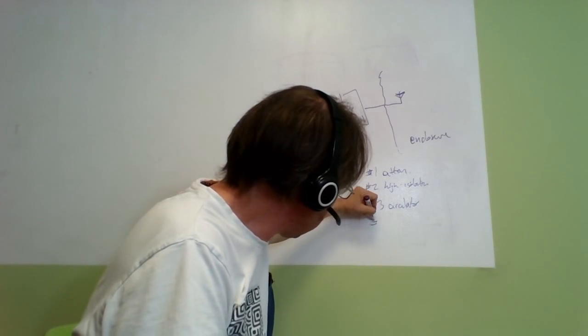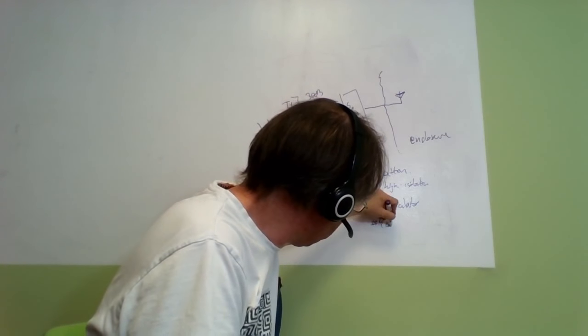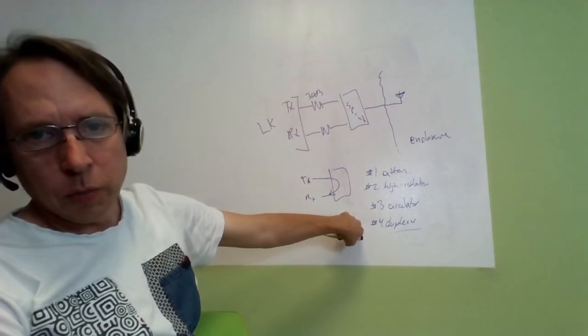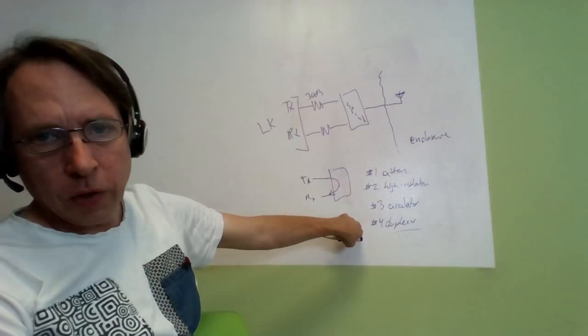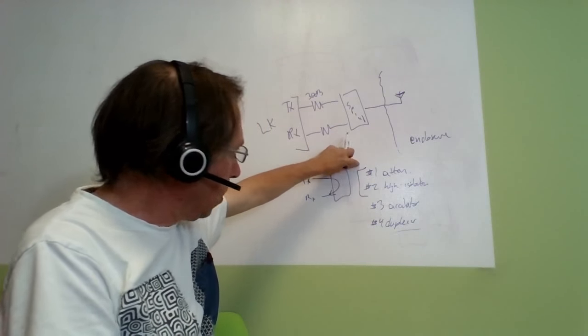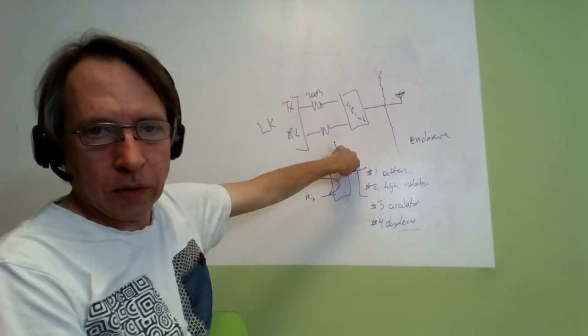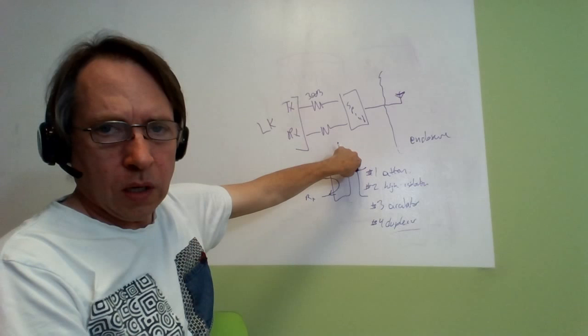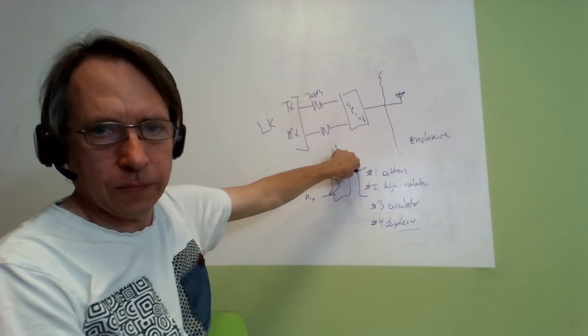And there's actually a fourth solution, which is to use a duplexer. And again, duplexers are band specific. These two solutions are not band specific. They can be used over huge bandwidths for almost any band. You can build a test fixture that'll work for almost any LTE band. I see we just lost the feed again.